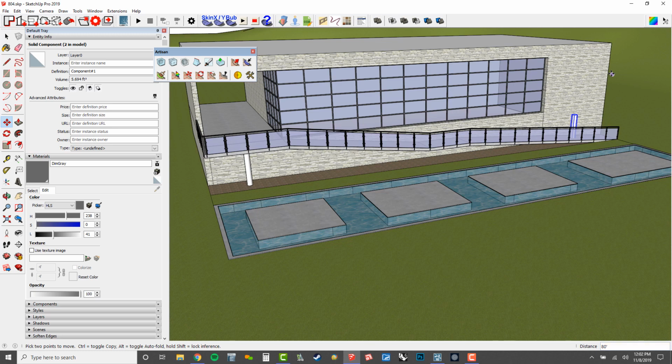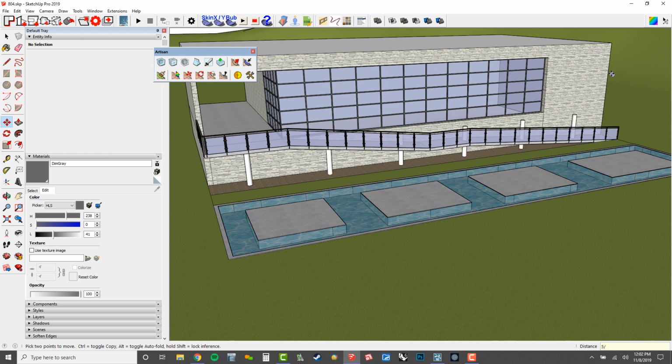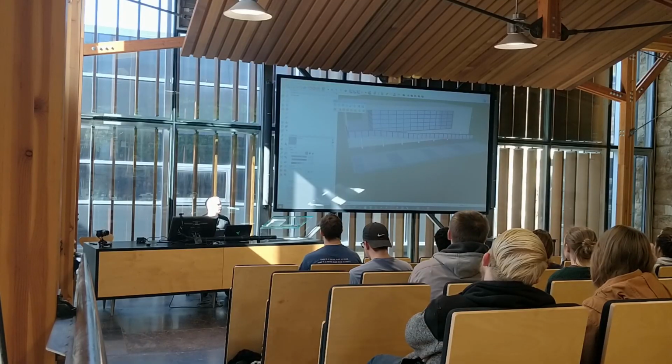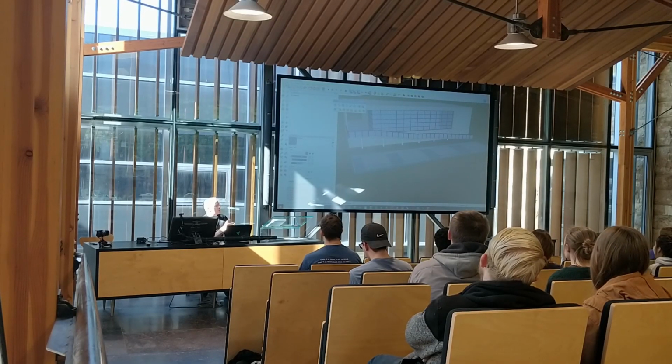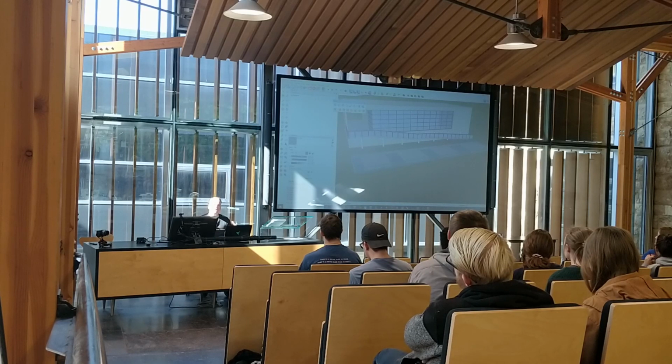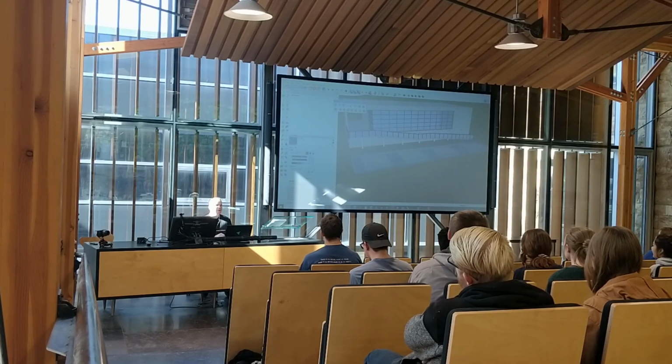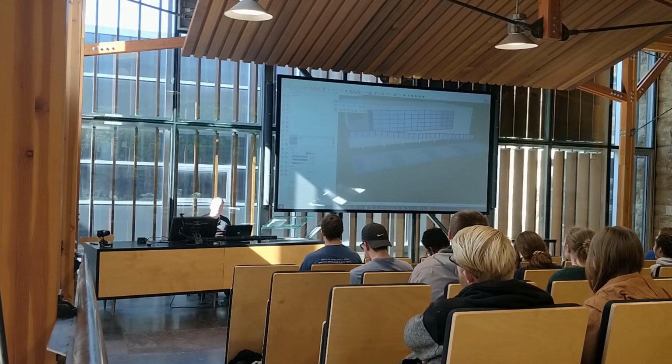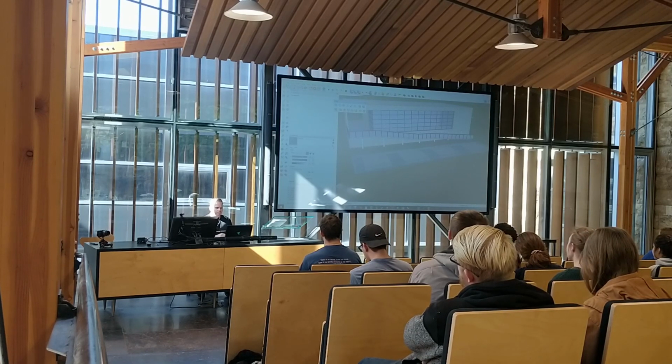The next thing I'm going to do is type in 5 divided by enter. And if I don't like that, I could say 12 divided by enter. And that's too much. Maybe 6 divided by enter. As long as I don't invoke another command, I can continue to make those design decisions. This works for shrubs, for windows, for any repeating element. You just type it in, make some adjustments. You don't have to hit Control-Z and back up and restart the command. Just re-input. In that measurements dialog box, it's always waiting for your input.